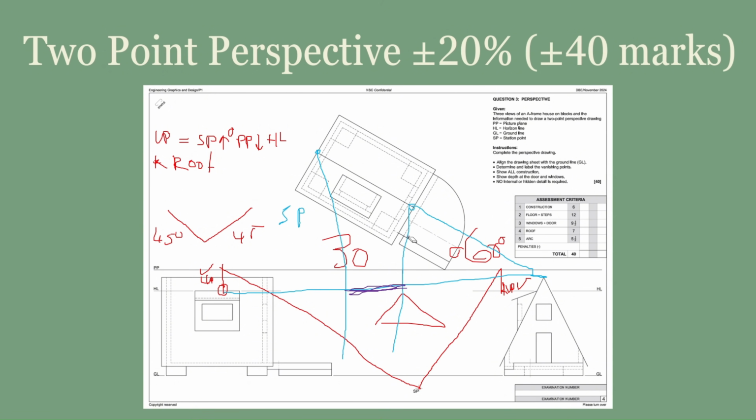It is also certain that you will need to be able to draw a circle or a half circle or just an arc in 2-point perspective. And when you need to do this, you need to divide a circle into 12 parts. But because this is only a quarter of a circle, we are going to get, I think it's 4 parts. Yes, this will be 1, 2, 3, and 4.